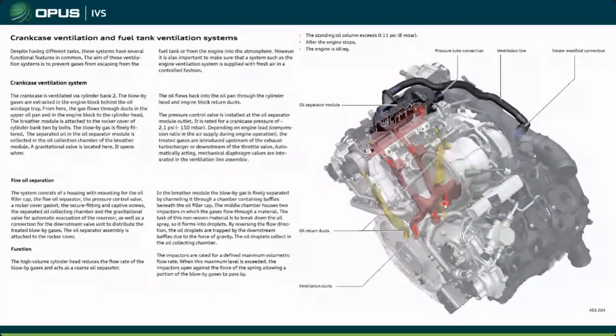And you'll see that this is kind of a reoccurring theme. These systems sort of work the same, have basically the same components, just sort of adapted to each engine separately. So I'm not going to bother reading through all of this. I'm just going to hit the highlights. The highlights are we're at 150 millibar crankcase pressure. That seems to be kind of where they're going. So at least now we have a number that we can check against.